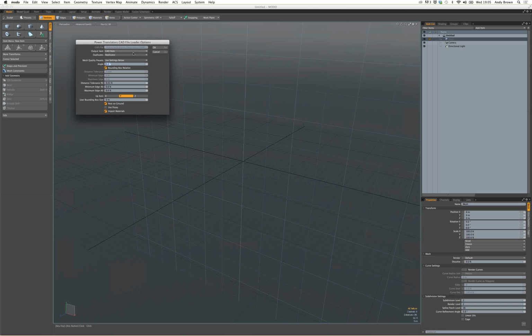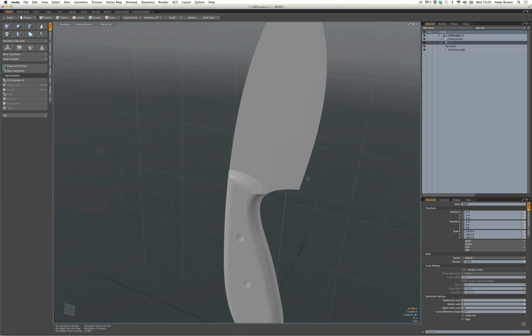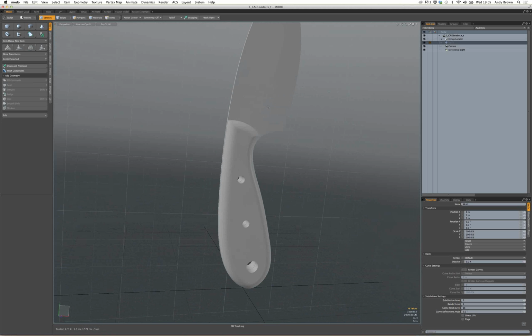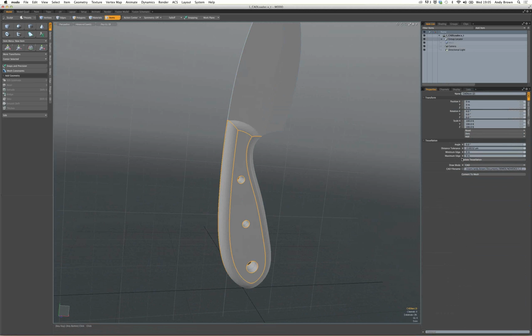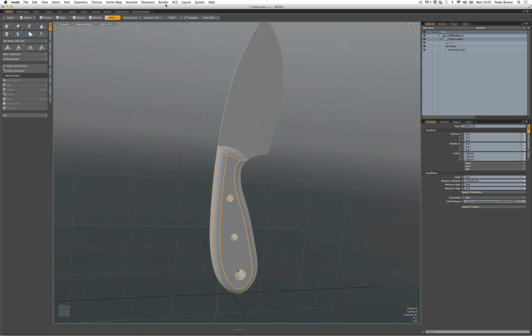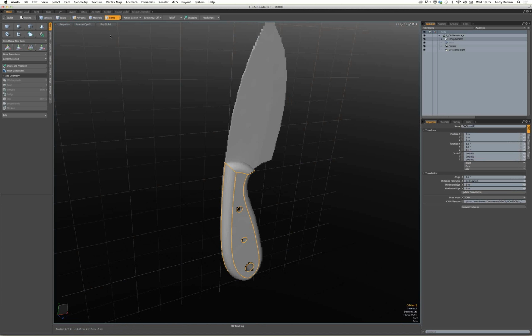So in this case, I'm going to load this Parasolid file, and I'm just going to load it in as a CAD item. And the reason I like doing that is when you load something as a CAD item, it doesn't actually tessellate anything when you load the file. If I just select some of these items here, you can see that we're actually seeing the surface data. So what the CAD loader is actually doing is referencing back to the CAD file. So over here in properties, you can see it's acting like a proxy. Now that can sit in your scene as reference. You can also render it and texture it on a kind of per item basis if you want to.